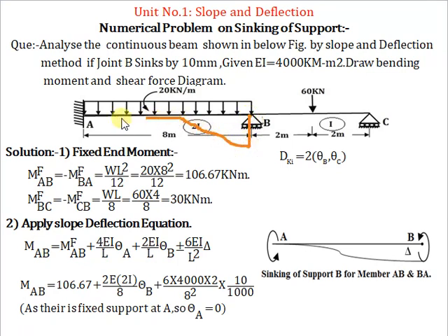this AB will get deflected and the moment will be created at B in the anti-clockwise direction. Start from the tension side. At the bottom there is tension, and move about the joint B in an anti-clockwise direction toward the open end. The same moment will be created in the same sense, anti-clockwise direction, at the far end.